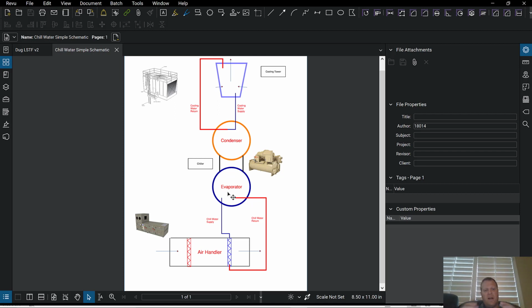from a liquid to a gas, and it's going to steal all the heat out of somewhere in order to make that phase change. Well, it's stealing all the heat out of this water supply. We have a pump pumping water to my little air handler schematic here, to the air handler coil, the chill water coil. A super simple schematic I drew up. Took me a few minutes.